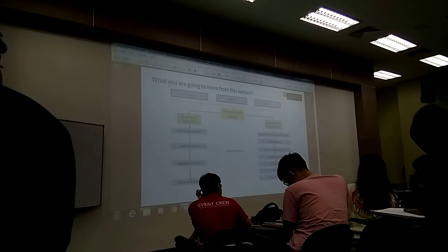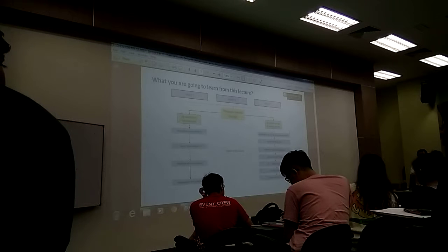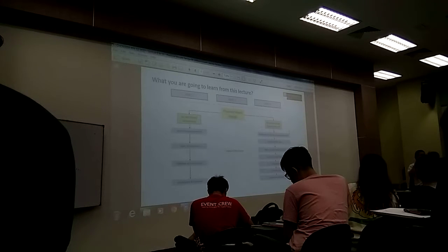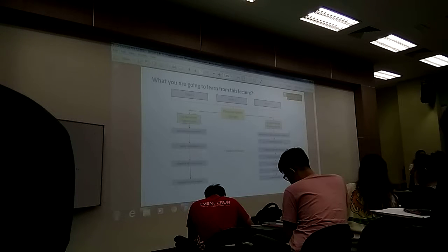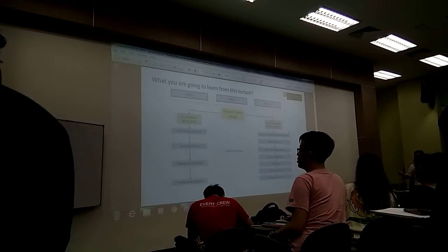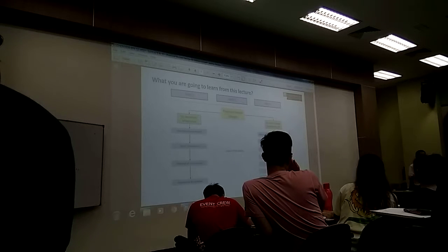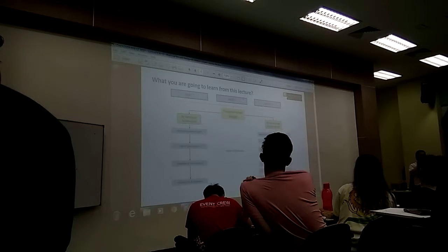And then joint efficiency factor, how to get them, depending on the degree of radiography and also the type of welding. This is specific for the butt welding type only. Okay? And then the equipment data sheet where you put all the calculations that you have.